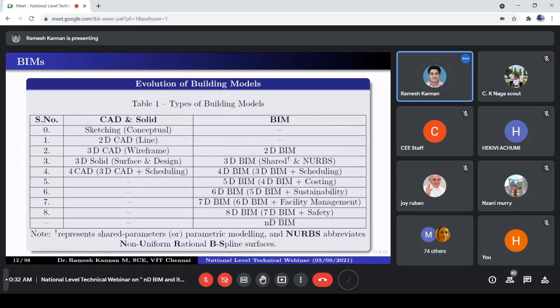And this is what nowadays the Revit suite is, which is architecture, structures, and systems, which is MEP: mechanical, electrical, and plumbing. Now, if you download Autodesk Revit, the entire thing comes as a unified package. Or if you want to use only architecture, without structures and systems, you may not have that much space on your computer, because Revit requires a high-end graphics card, and the software itself is very heavy, more than 10 GB. So if you don't have the space, and you're working with only architecture, then you can download Revit LT, for cloud sharing and work sharing. And then there are auxiliary software like Autodesk Formit and Autodesk BIM 360, with which you can even visualize your BIM models. You can even use a mobile phone to download these apps, and visualize the models generated using Autodesk Revit.